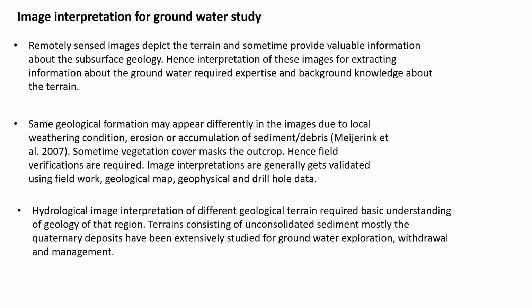Moving to the next: image interpretation for groundwater study. Remote sensing images depict the terrain and sometimes provide valuable information about the subsurface geology. Hence, interpretation of these images for extracting information about groundwater requires expertise and background knowledge about the terrain. The same geological formation may appear differently in the image due to local weathering conditions, erosion, or accumulation of sediment and debris. Sometimes vegetation cover masks the outcrop. Hence, field verification is required.